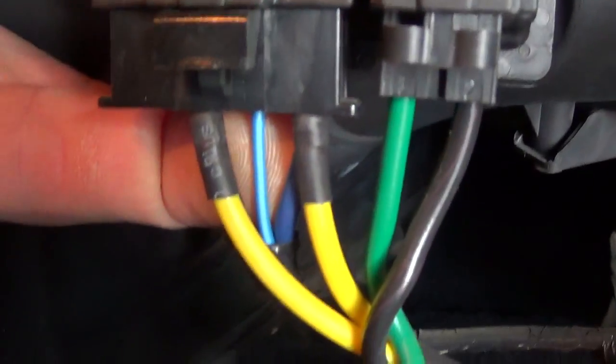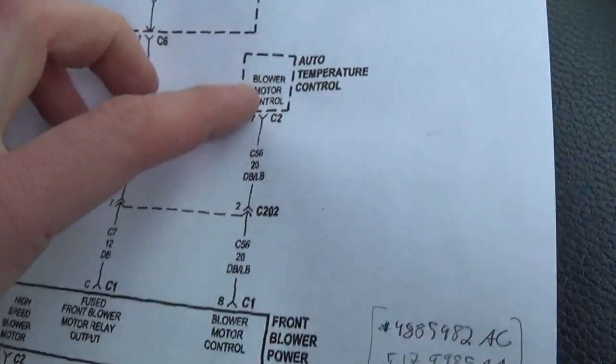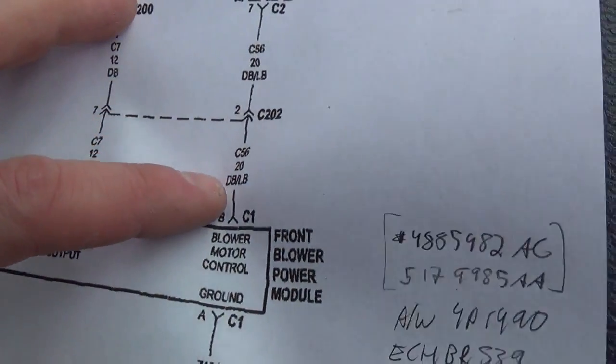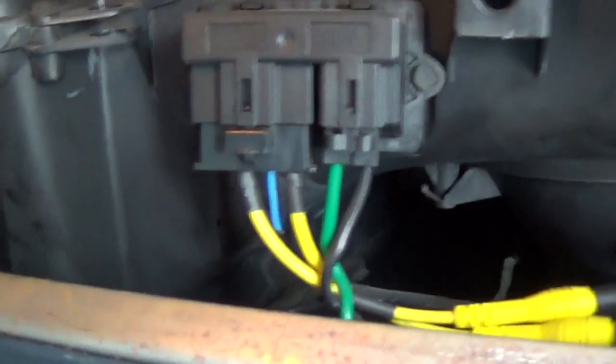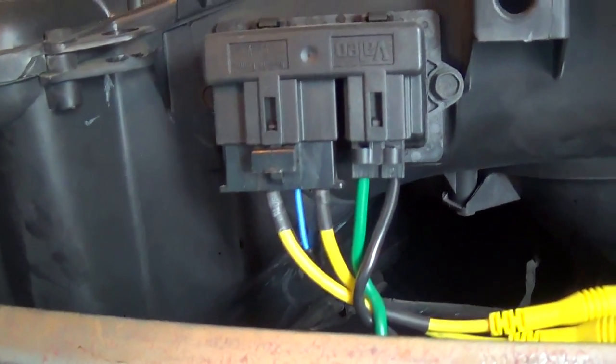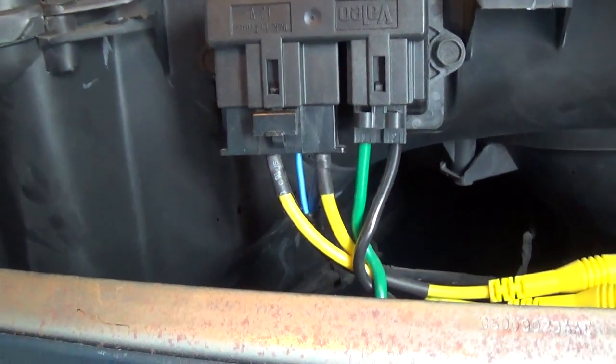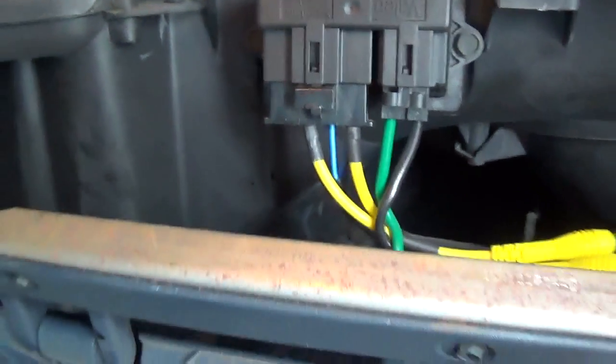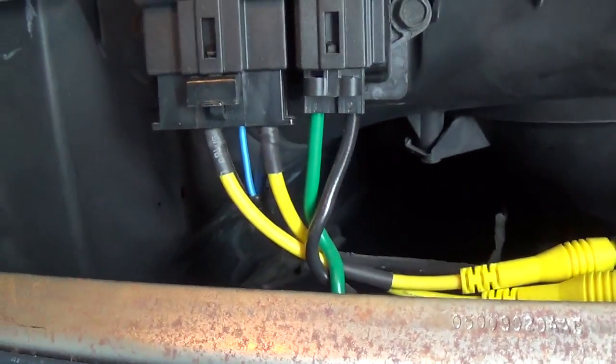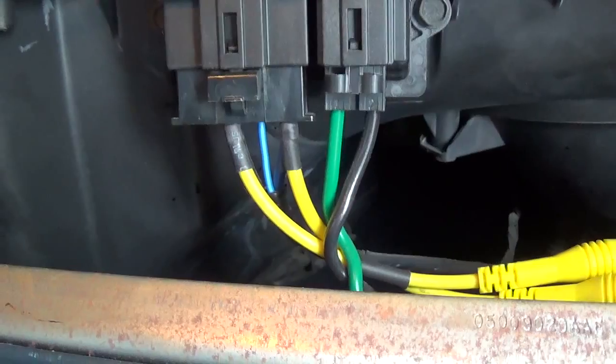That little skinny light blue wire, which comes from our blower control, dark blue, light blue. And that we need a scope for because it's pulse width modulated. We could use a voltmeter. Yeah, let's do that. Let's stay primitive for now. I don't feel like firing up the Verus in this cold. But if we don't see a change with the voltmeter, then we can hook up our scope.